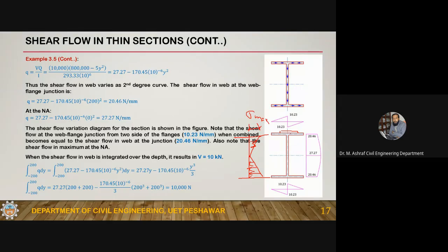The flexure formula says stress is equal to M over S, or My over I. S is the section modulus, you know this. The section modulus will get increased if you are increasing the area of these flanges.